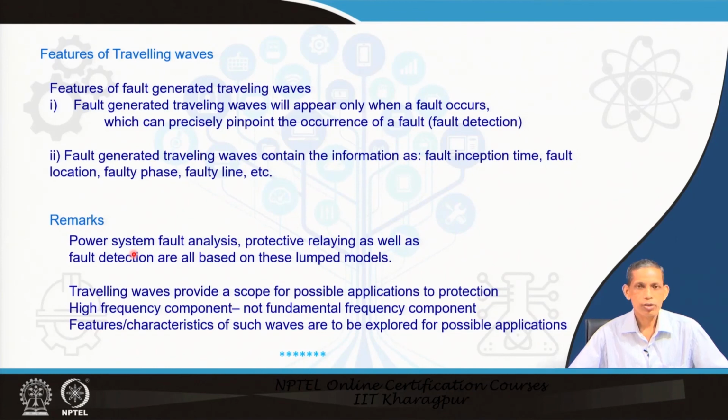Overall, power system fault analysis, which we carried out in earlier lectures, protective relaying as well as fault detection, are based on lumped models. Our analysis used lumped models and sequence component analysis, but in actuality, for proper modeling of the systems, we require the distributed model, and travelling wave is based on the distributed model. Therefore, this is more accurate in that perspective.